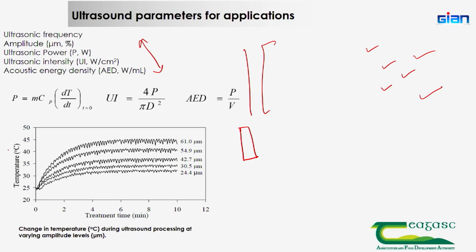They cannot be kept facing each other like this. You read it correctly. Because if sound pressure comes from here and from here, two different frequencies, it will destroy the transducer. So it has to be in perfect alignment.